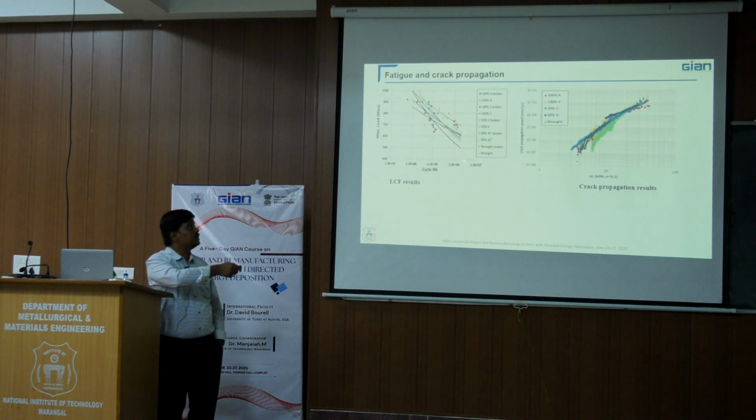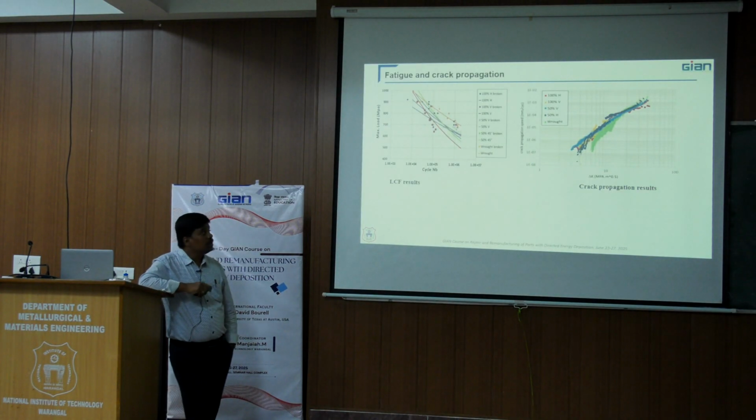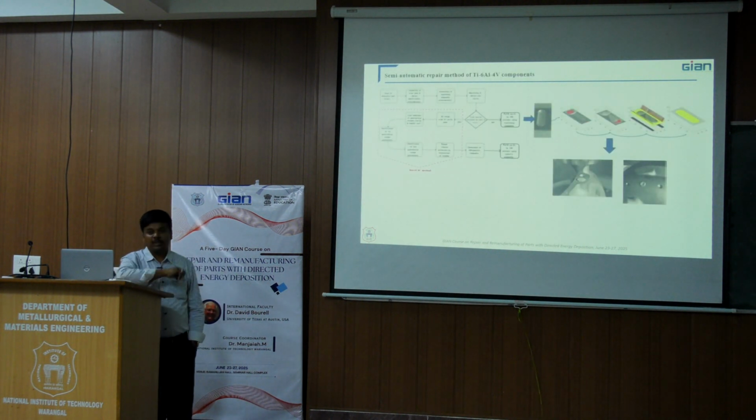And we have also tested, as I told, the fatigue properties and the crack propagation properties. You will see that the fatigue properties in all the conditions are matching with respect to wrought, even in the crack propagation. Then we tried to address how we can repair some real components.